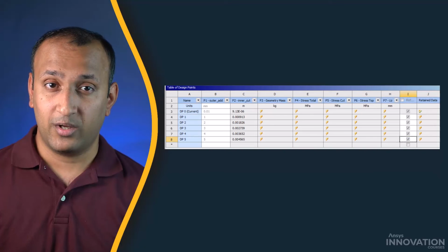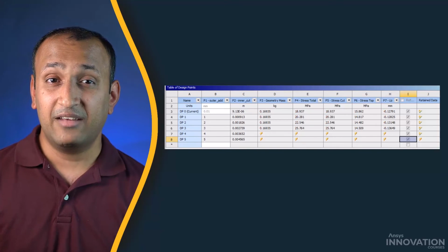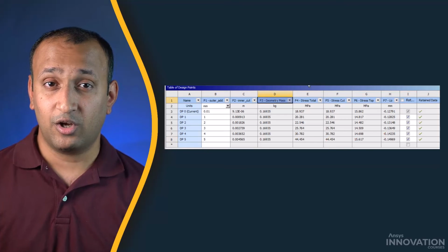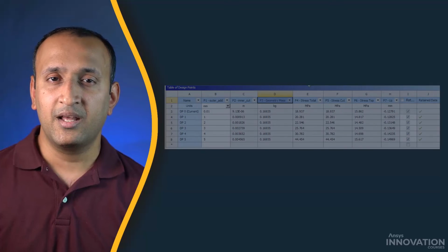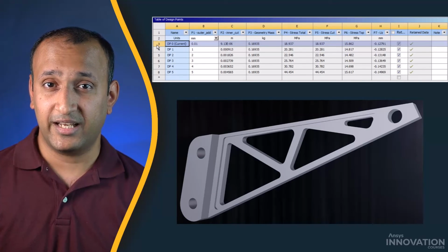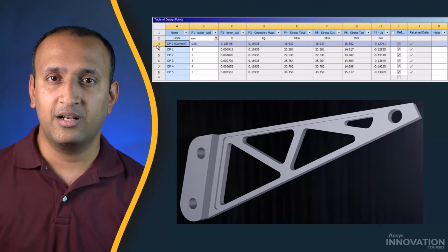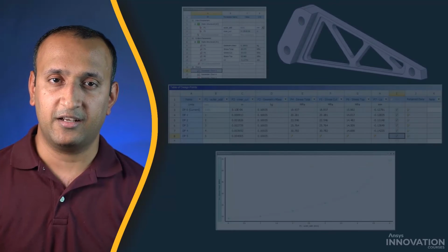We set up the model once and just run it, and it runs 6 cases automatically, giving us insight that the geometric changes aren't linearly related to the stress or displacements, even though this is a linear analysis. We see that the initial design is the best, so if presented with this design change, we can say with more confidence that the design change won't be favorable to the structural response. This completes a demonstration on how to set up, solve, and post-process a parametric model in Ansys Mechanical.